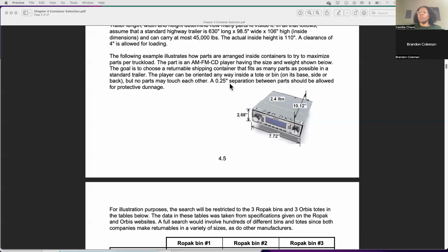So this is telling you that this part needs protection. You've got some Class A surfaces on this side, but you also know that you've got things like buttons or knobs that could get knocked off. Here on this side, you might have some venting or some cuts in the sheet metal, and those may be sensitive to getting hit. Maybe they have to be in a certain exact position